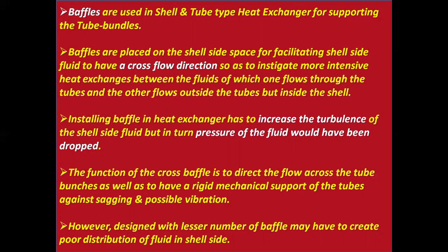Baffles are used in shell and tube type heat exchangers for supporting the tube bundles. Baffles are placed in the shell side space to make the shell side fluid have a cross flow direction, so as to instigate more intensive heat exchange between the fluids, of which one flows through the tubes and the other flows outside the tubes but inside the shell.